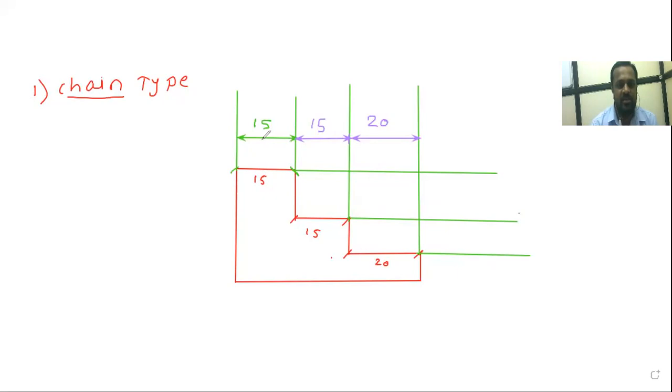See, this is the first dimensioning line, here it ends. Again, from this arrow, we have to draw another dimensioning line and show the dimension for this part. Suppose this is part 1, part 2, part 3. For each part we are showing the dimension individually in a continuous format, or we can say in chain type. Now in this side also we have to show the dimension. Please tell me how to show the chain type dimension for this side.